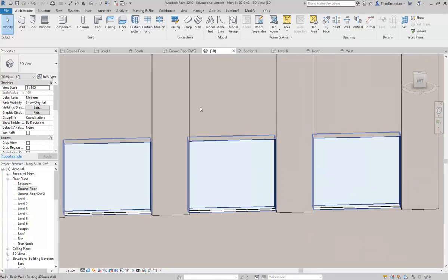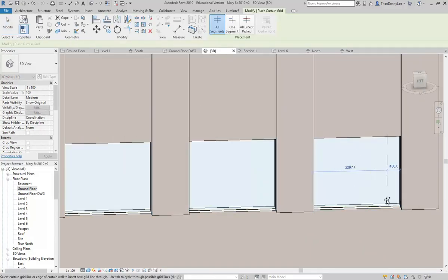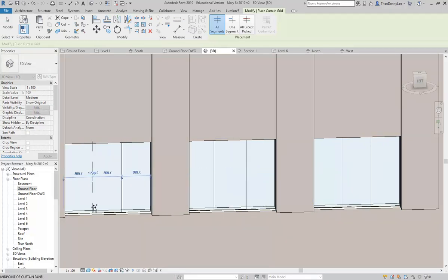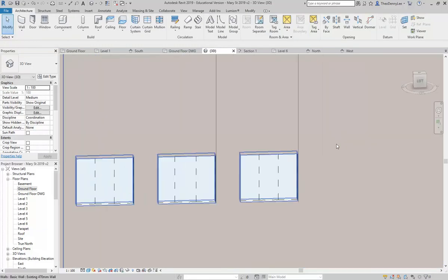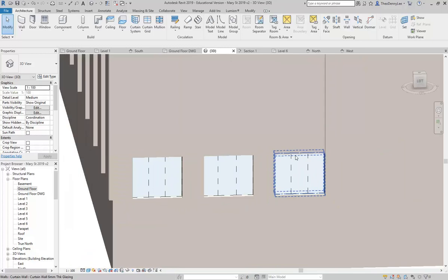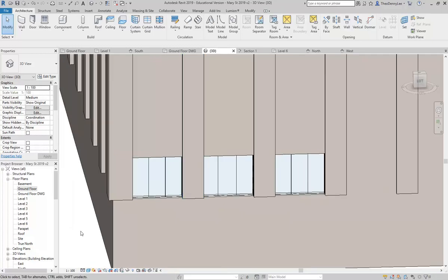And then maybe if you want to have a go at putting some grids in, you can try putting some curtain grids by eye inside those openings just to get an idea of some divisions. Don't worry about the measurements, it's just very rough for now. So if you can get that far, then you're doing well. But it's a good way just to get used to using curtain walls, especially in a shop front. Yeah, easiest to draw them in the plan though, in the ground floor plan.